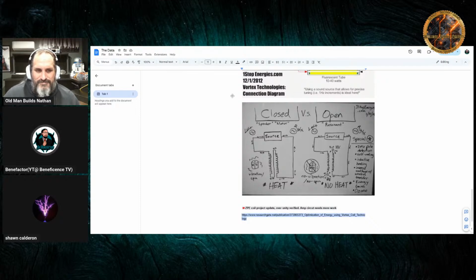He didn't talk about this, but Michael and I kind of devised this method of using the wireless induction as an indicator as well. So if you have two coils that you're testing with, leave one on top of one that's not connected. Just put a little LED connected to the start and finish of one of the output channels. And that's all you have to do, just leave it there. Then you can sweep through the frequencies and find that sweet spot by looking at the light up. So yeah, using LEDs as indicators helped me so much with my ZVSs.